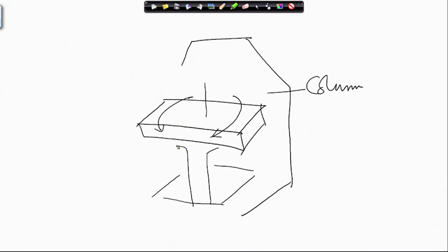If it has motion about a horizontal axis, it will be called omniversal. That is a little rare. If the cutter axis is horizontal, it is called a horizontal milling machine. If the cutter axis is vertical, it is called a vertical milling machine. If it is to have this rotational motion of the table, it has to have bevel gear connections which will allow it to rotate.